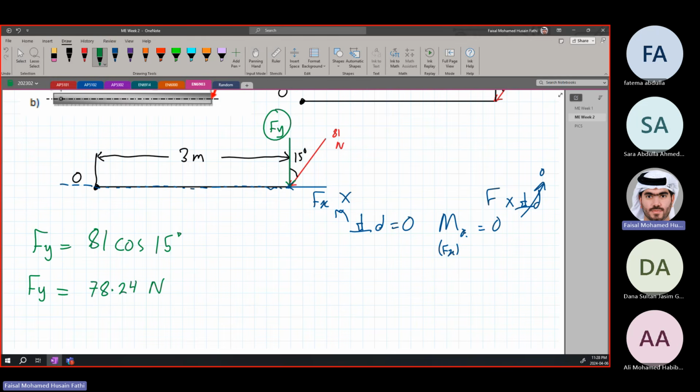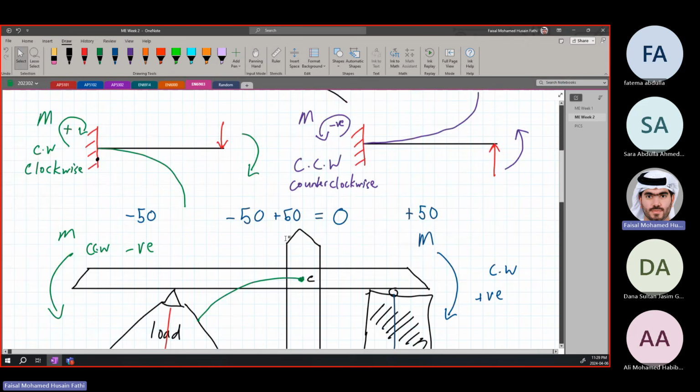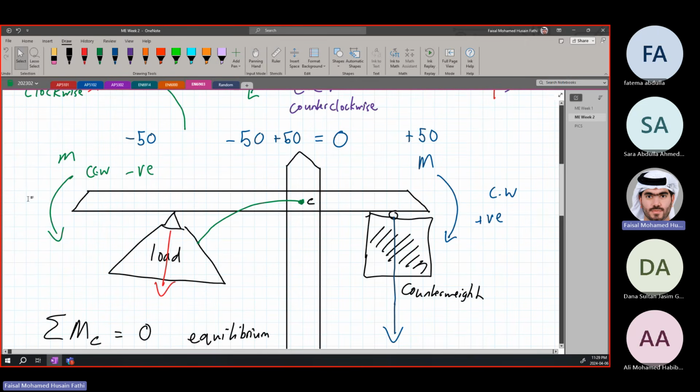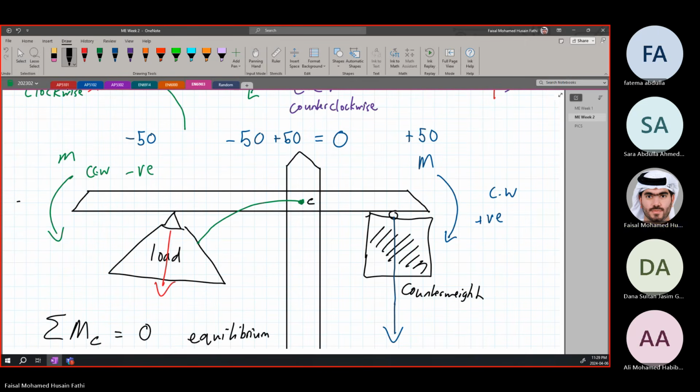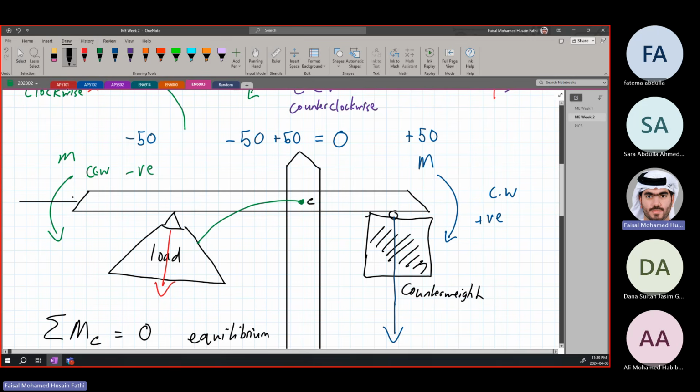Why? Because if we go back to the original concept of the crane, if we apply a force on the crane here, if we are pushing the crane from here, it is not going to cause any moments. It doesn't cause bending up and down. Right? It makes sense, because it is going to be just along the same line, so it cannot bend around it. If you have a pen or pencil in your hand and you want to break it, you're going to bend it.